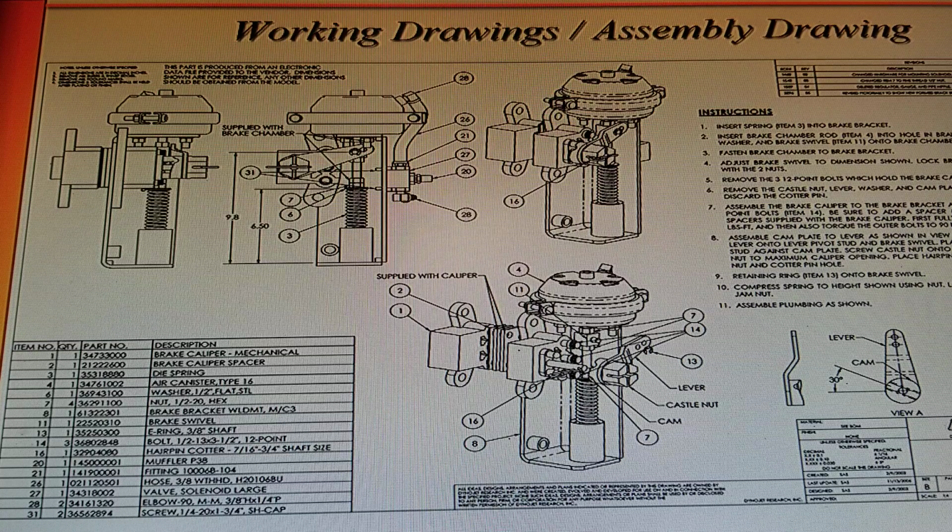The table there has about 4 or 5 revisions, where along the history of this drawing somebody's made changes to it. The lower left is the parts list, or the BOM, bill of material. Each part has a number, which corresponds with the item number. If you look on the drawing itself, you see what we call balloons.